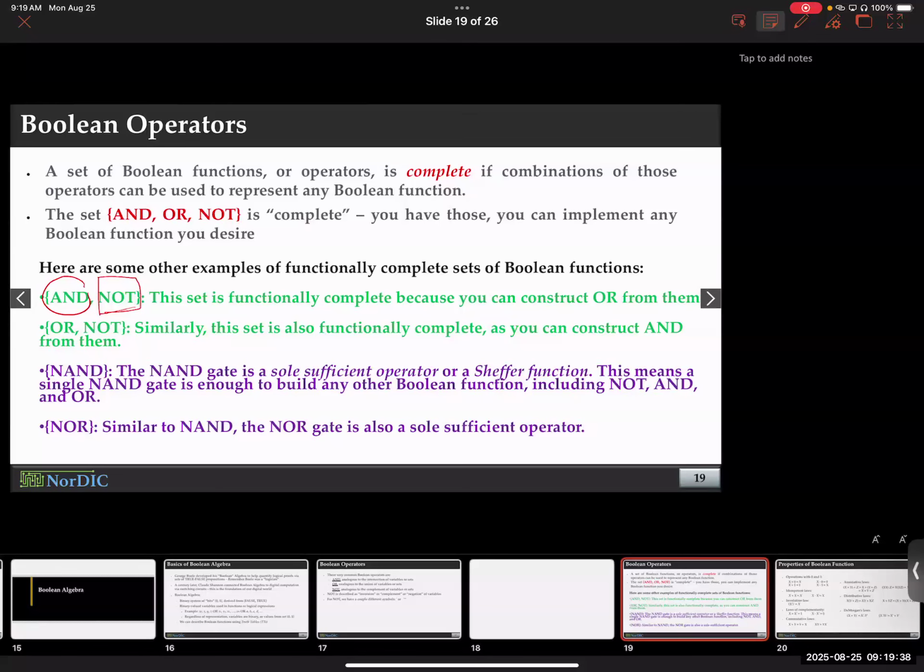First, we start with, if you give me AND, OR, and NOT, I can do anything. Great. Then I say, okay, let's bargain a little bit. Let's not do OR. Just give me AND and invert. I can do anything. You see my point here? Well, you can always get more, but if you could do it with less, that's even better. So instead of AND, OR, and NOT, I could just do AND and NOT, or OR and NOT. The reason is AND and NOT could be combined to make, anybody can guess?